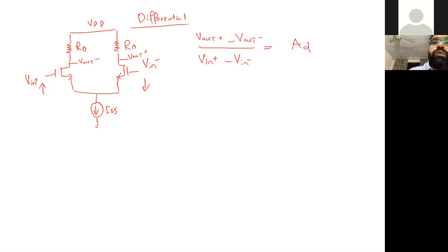So now we know that if you have a differential pair, it's going to be symmetric. This is going to be AC ground. Why AC ground? Same amount if V in increases here, the same amount V in negative decreases. Ultimately, no current will flow through this point. So it's a virtual ground and an AC ground. So we can use it as a ground, and that helps us. We can sort out our circuit in a similar manner.